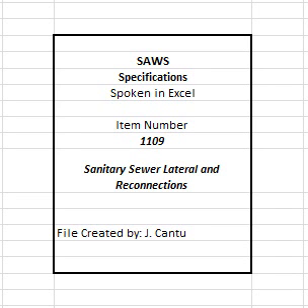E. Remove and replace cracked, offset, or leaking service line for up to 10 feet, measured horizontally, from the center of the new main or liner. F. Make up the connection between new main or liner and lateral using PVC sewer pipe, with approved fittings and couplings. G. Encase the entire lateral connection in cement stabilized sand as shown in the contract documents. H. Test each lateral connection before backfilling.